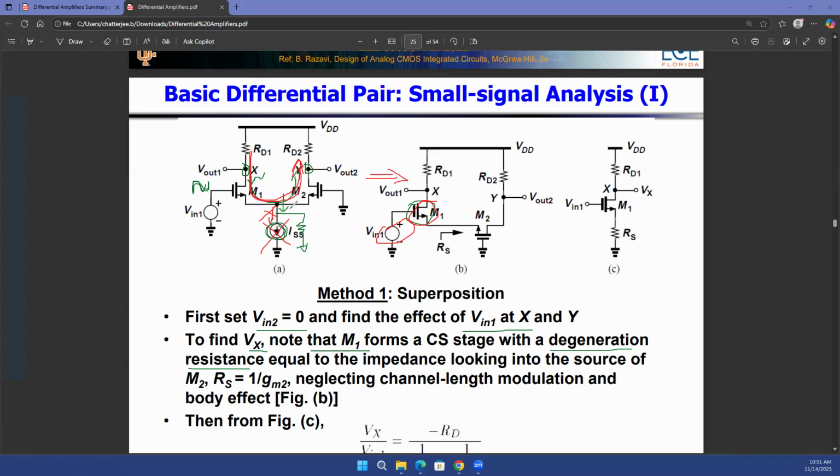By ignoring, what I mean is that I'm making sure that the DC current source is open. A DC voltage source, you can make it shorted to ground when you're doing AC analysis. It's the same thing that we had done before as well.